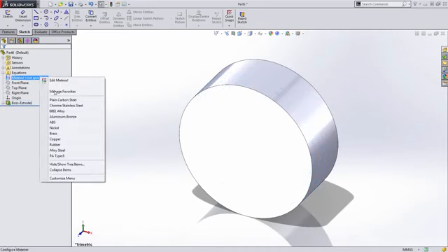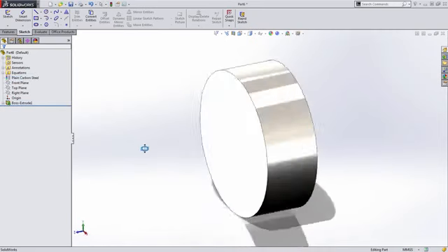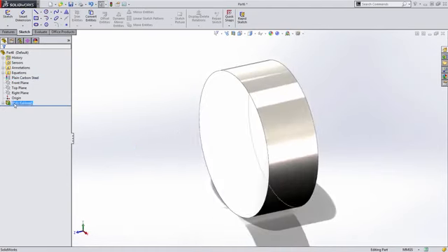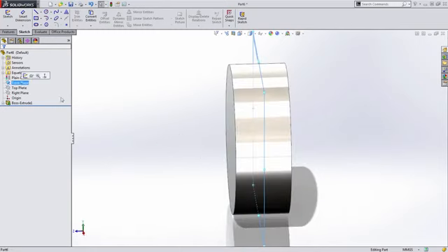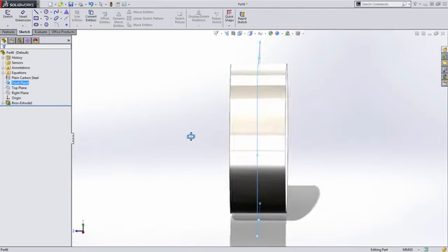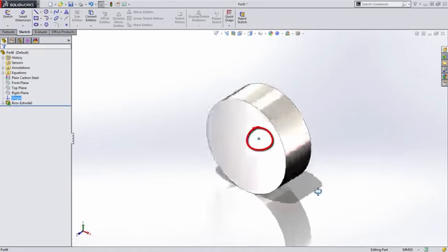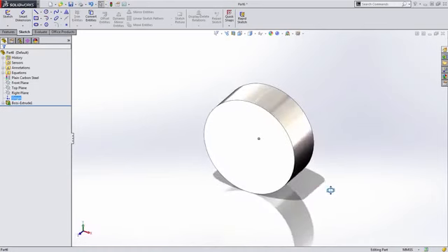For good measure, we're going to set the material to make sure our part's more physically or visually appealing. So one of the things I just mentioned is that I used a mid-plane extrusion. This is actually really important. This sets the front plane right down the center of our part. Not as important for creating spur gears, but when we create the helical gear later on, it'll become more apparent. Likewise, the origin is in the center of our part, directly in the center. This gives us the ability to reference that point throughout our design, and this is often an overlooked yet critical part of working in a parametric design tool.